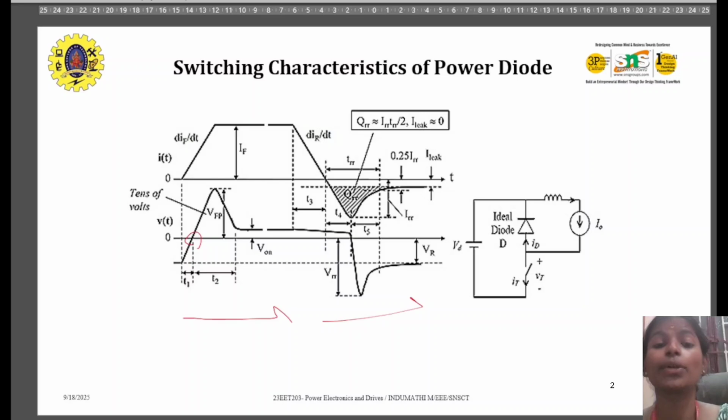So when the diode goes from forward conduction to reverse bias, stored charge carriers continue conduction for a short time, and it causes reverse current to flow through the diode, even though it should block. So here we have storage time. The storage time is when reverse current stays high while stored charge is removed, and transition time is when reverse current reduces to zero.